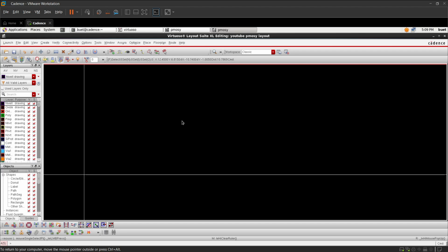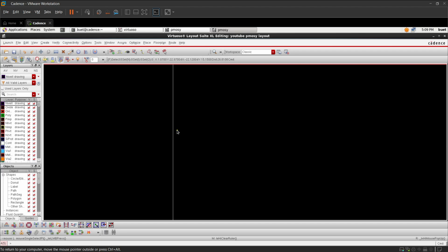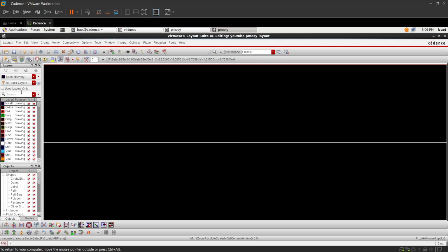Okay. Next, shift key. So this will disappear all the scales. So we'll be doing our layout. Press F. Firstly, we have to take our oxide. You can go over here, search for oxide. In some of the technologies, it is shown as UOD, but you can go with the oxide. Okay. Press R.